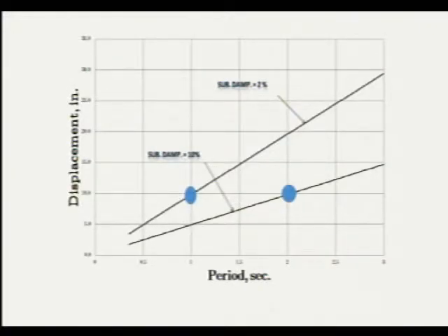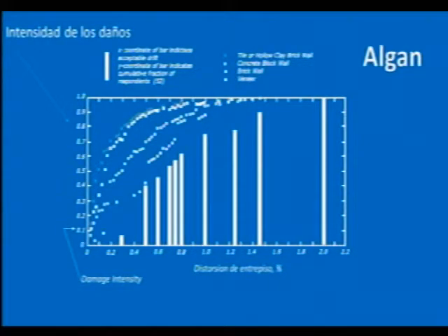If you think of the same picture in terms of displacement response in a single degree of freedom system plotted versus period, as the system goes from 1 second to 2 seconds, the damping increases, so the displacement remains about the same. Hey, do you see, I'm in a way denying science. I'm saying that the drift doesn't increase with respect to the linear model. But that's what it was. I didn't accept it, because it didn't seem to satisfy.